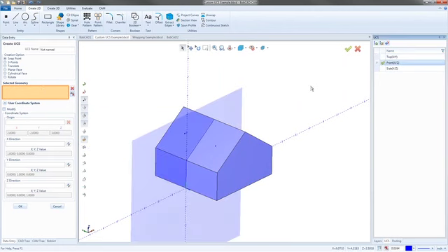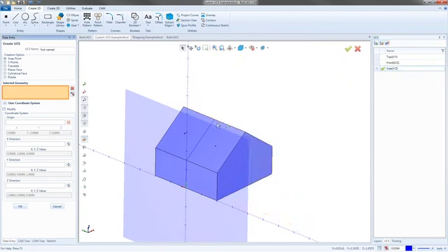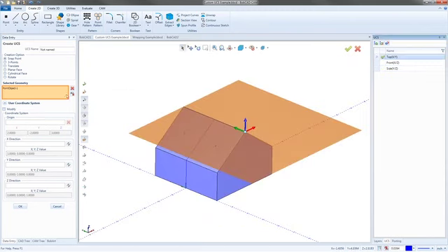Now if I go to a front plane, so I set it up with a front plane first, and then I go pick the same point, now I'll get a coordinate system and a plane that matches the front plane, but is now moved to that location. So it's still flat. It's just calling basically this front face here 0 instead of halfway down the part. And then the last one would be side. Same kind of thing. You just clear this out. As soon as you pick one, it's going to automatically jump to that position and snap to it in the orientation based on whatever plane you were in or whatever UCS you were in before you click the point. So leave it on point there and get rid of this thing.